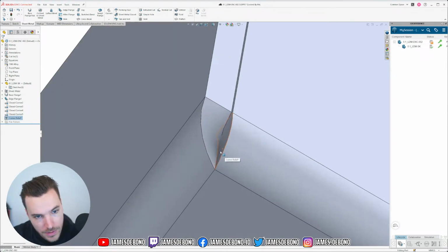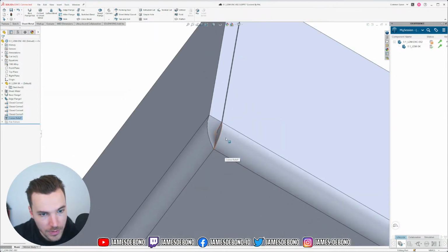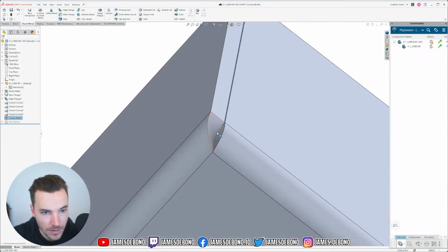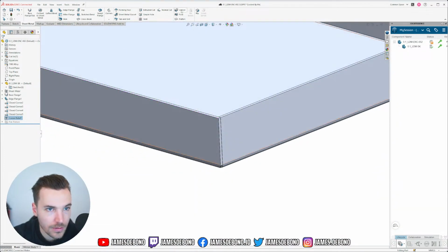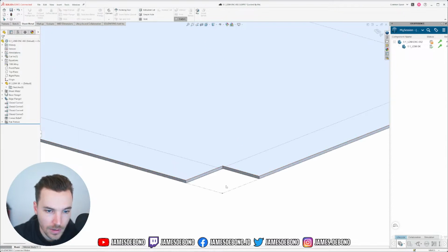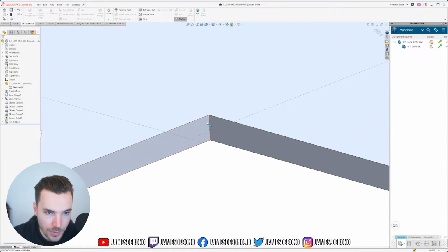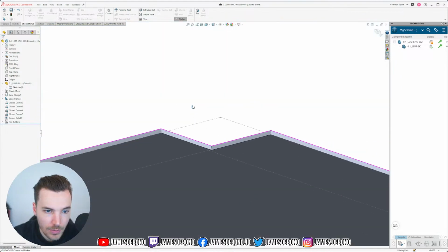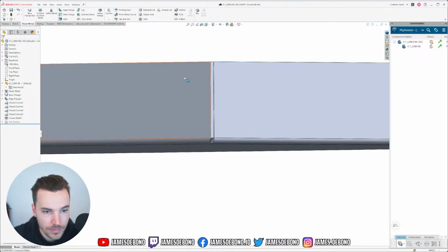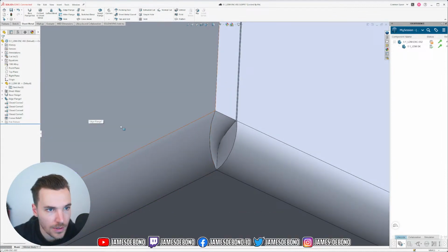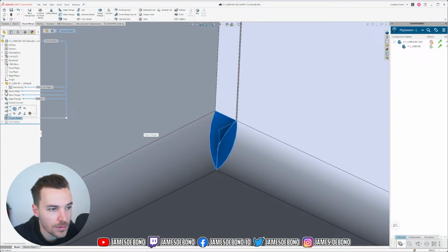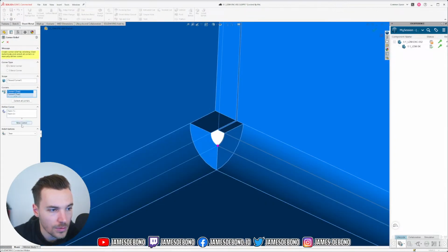And this closes the gap the most, but when you do the flat pattern, so if I flatten this, you have a sharp corner there, which is fine, but it's not ideal. A curved corner is much nicer, especially for laser cutting and stuff. So, I'll show you what other ones we have.